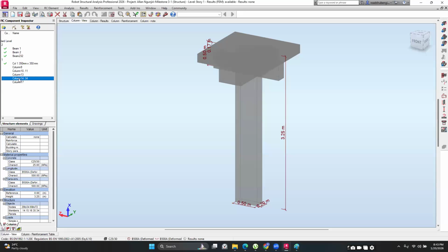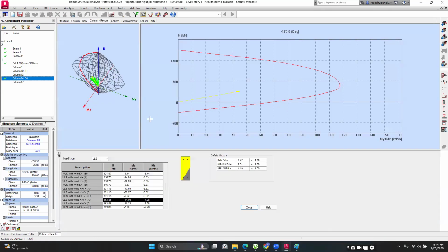So you just select the one with the range, and then you click on reinforcement. So select the columns reinforcement pattern, then the column calculation options for the columns, and then the story parameters. And then once you do that, you just click on calculate. Remember, we had set these ones earlier, and then you can just go through the results. You can see the interactive diagram. You can see for this one, it's not as large as the other one was.